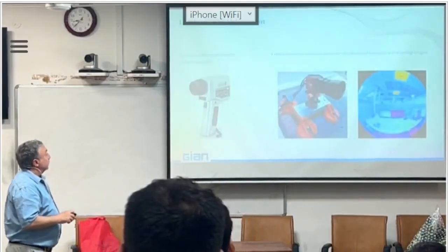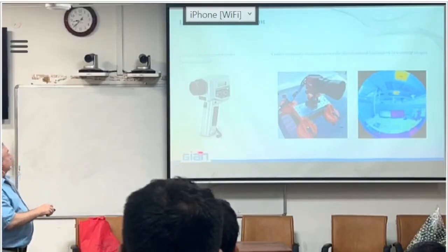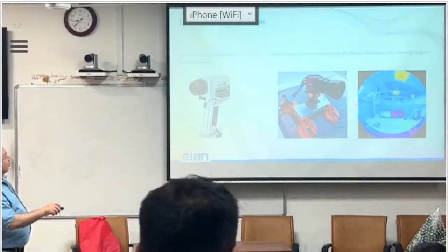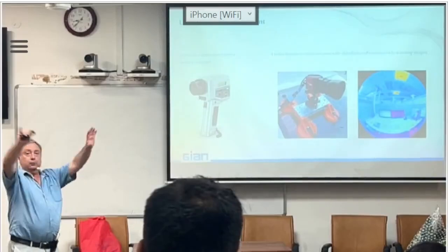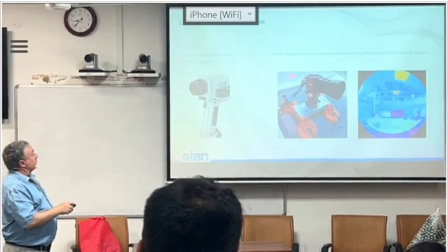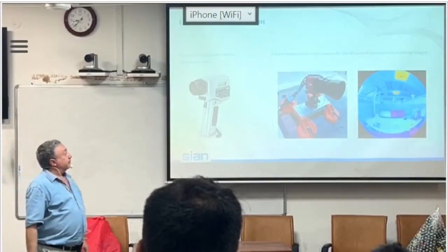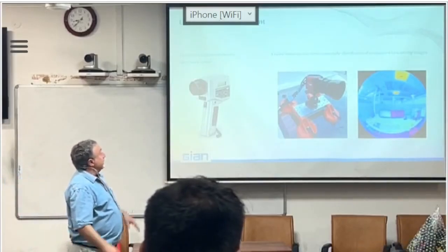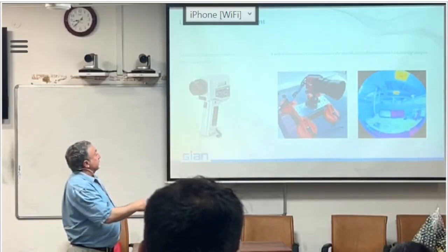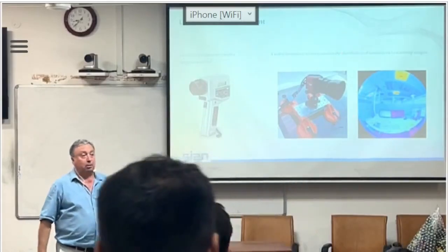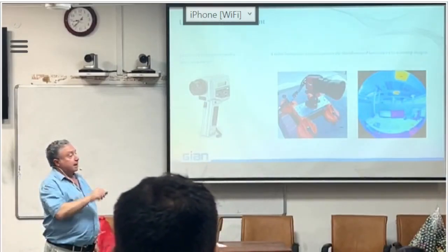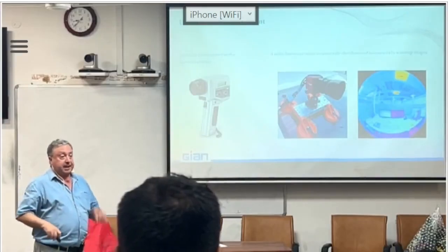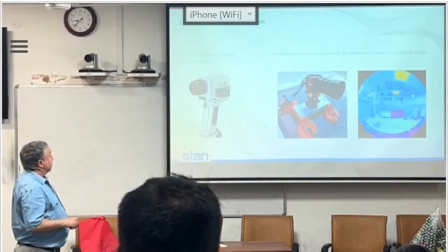How do we measure that? We measure it either with luminance meters, of this kind, if you want to measure one point. If you want to measure the full space, you can use video luminance meters, which are cameras or photo devices that can get the luminance everywhere in the space with one shot.